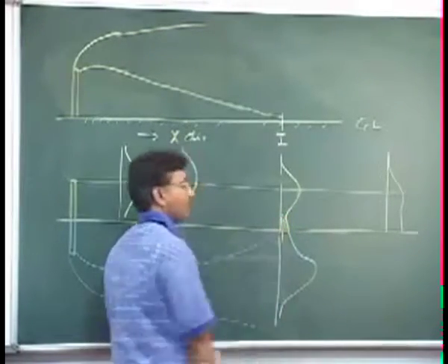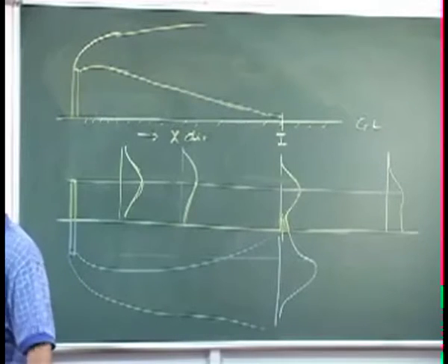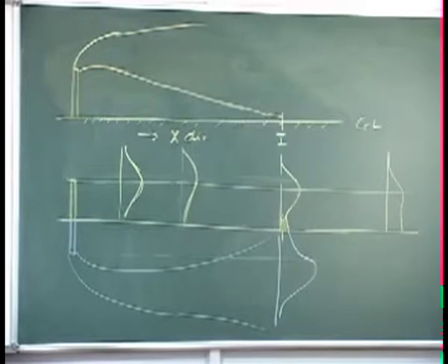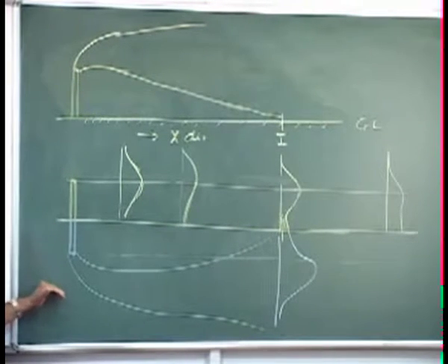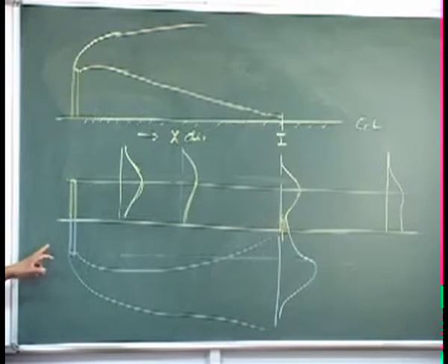And I must account for this change. I must account for the reflection of my plume, and I account for that as if this is an inverted source. I can write the same equation for this particular source. Earlier we put z equals z minus h for this source.